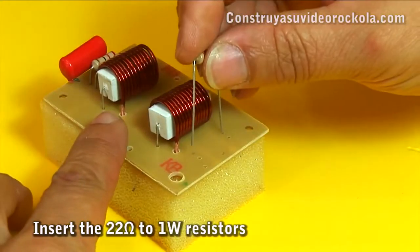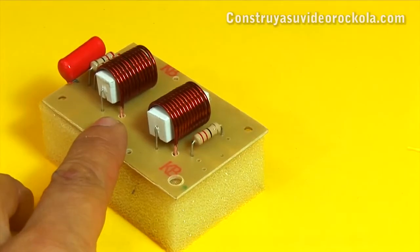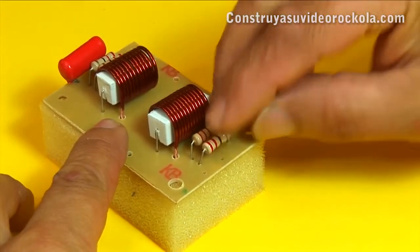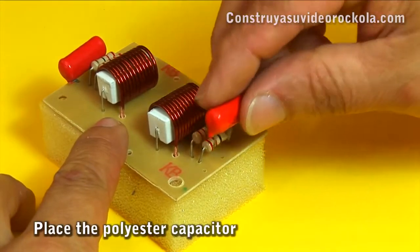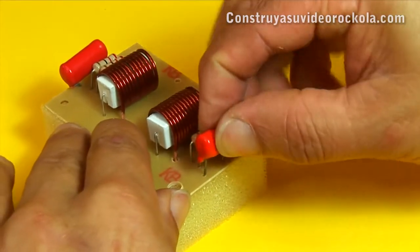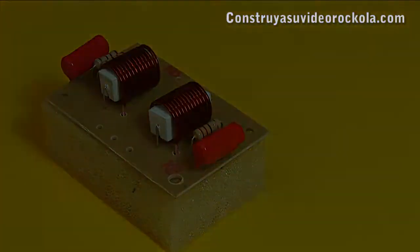We place the other 2 resistors of 22 ohms, at 1 watt. And finally, we place the 0.1 microfarad capacitor. Remember to use as a guide the component mask, delivered in the PDF file.